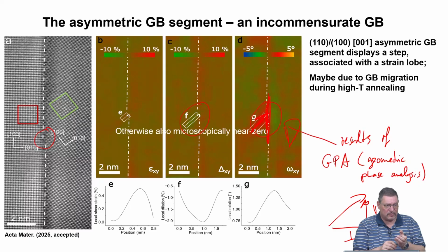Here we do not have stress-free conditions. So it means that these grain boundary defects, as long as they are there, create situations where we have to treat boundaries and transport along boundaries as acting under an additional force field, which comes from defects of defects, like these steps in grain boundaries. Maybe the effects are not so high, we don't know yet, because diffusion measurements are still running and we don't have results yet. But it's something which is new and which you will not find in textbooks or papers, because so far this has not been reported.